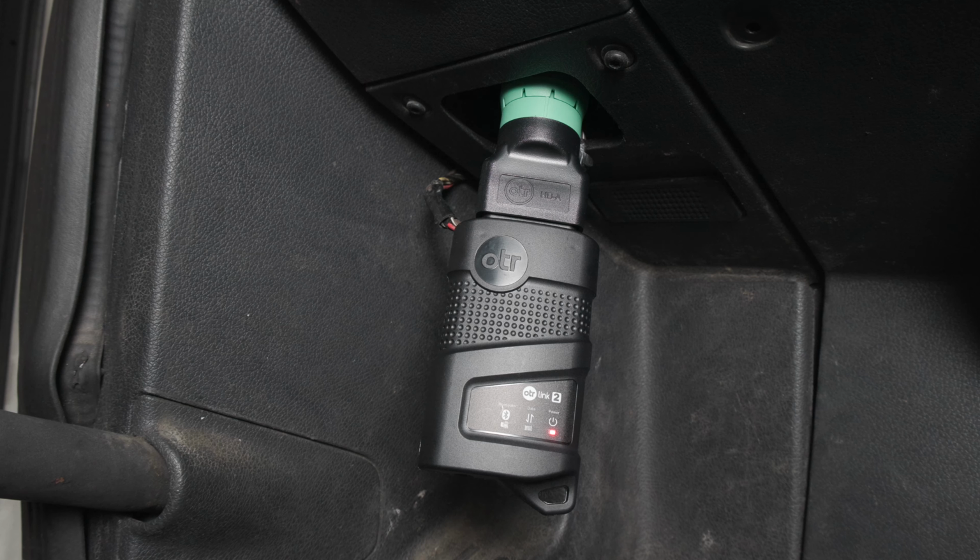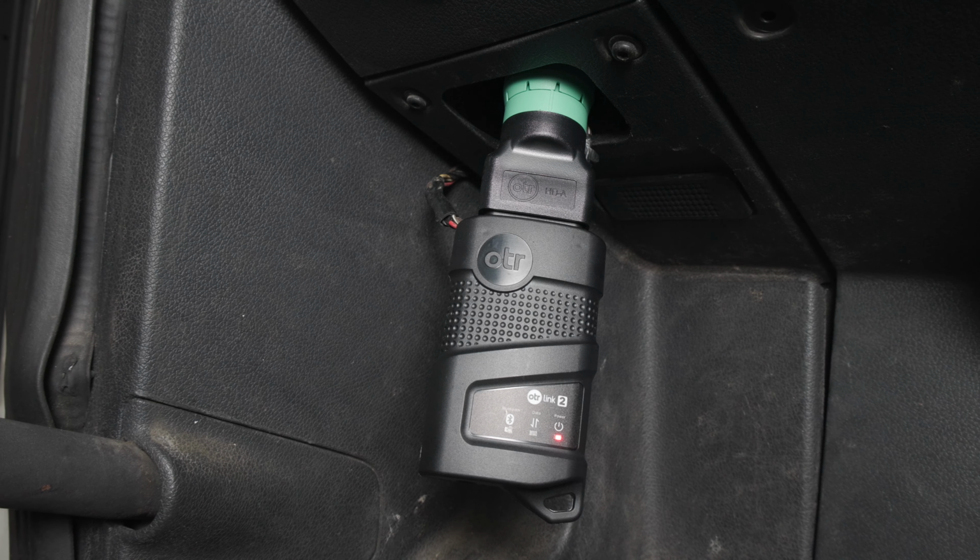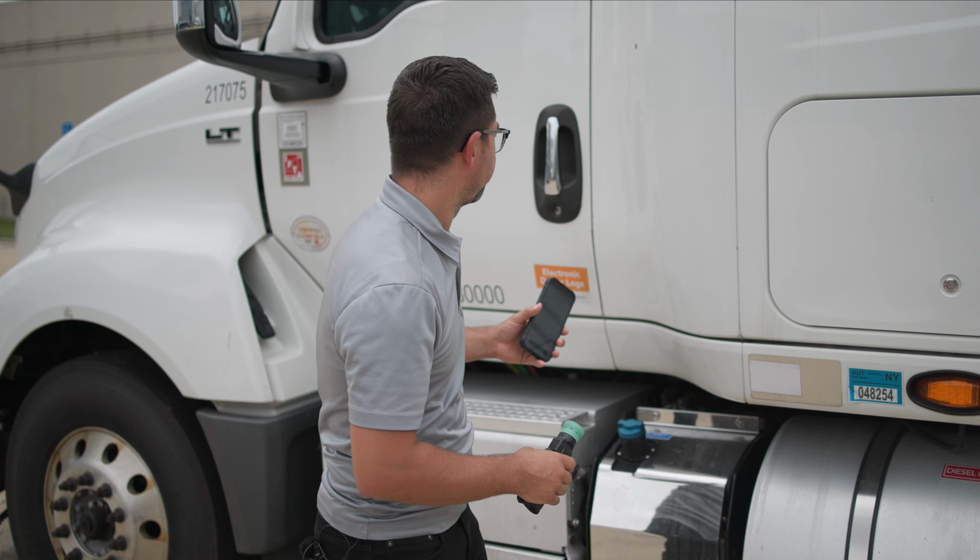to this truck, and what this uses is a 9-pin diagnostic plug, which is located right next to your foot at the kick panel on the side of the truck. So we're gonna go ahead and get it connected. We're gonna make sure that the key is in the on position. Then we're gonna open up OTR Diagnostics to get connected to this truck. I'm just gonna show you that, and then we're gonna go to the dashboard and check out what capabilities OTR Diagnostics gives us on this truck.